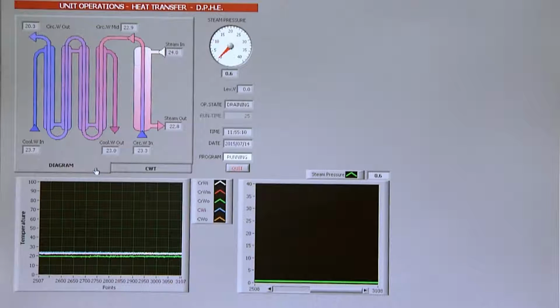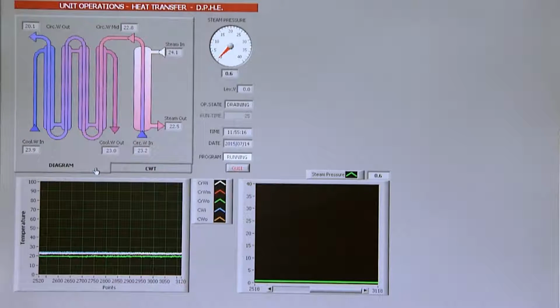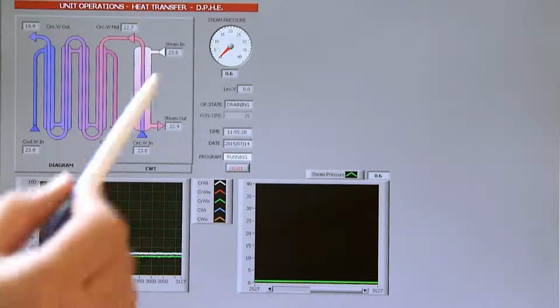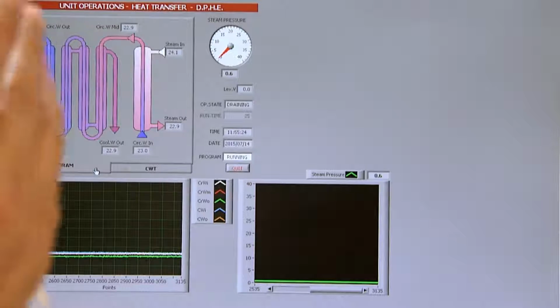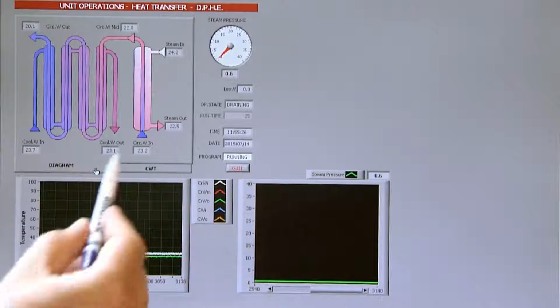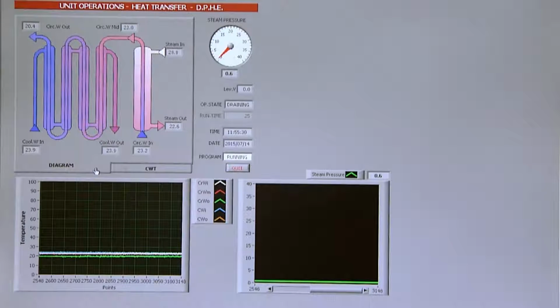First, the condensate might have already cooled down a little bit because it accumulates a little bit here in the bottom. Second, the thermocouple is located in a pipe that's kind of popping out, so it gets cooled down by the environment. So be careful with this reading. Don't necessarily take it as an absolutely correct value.